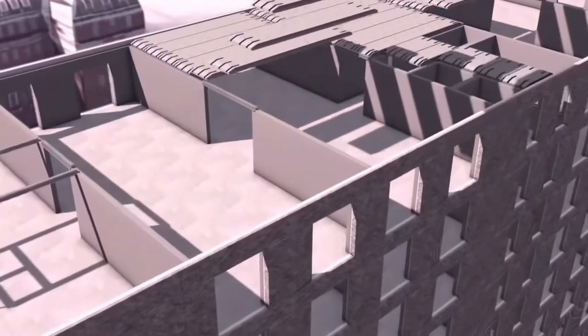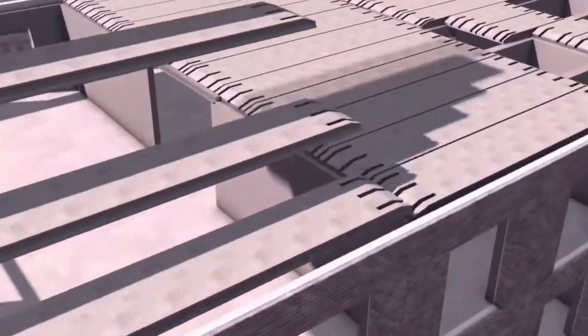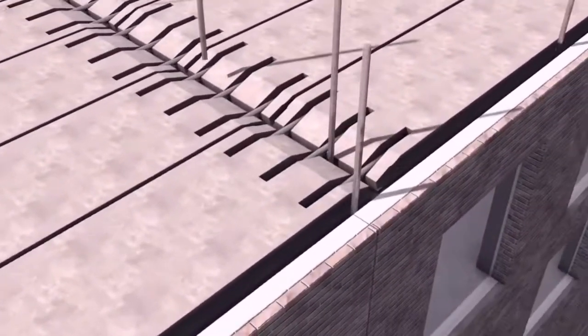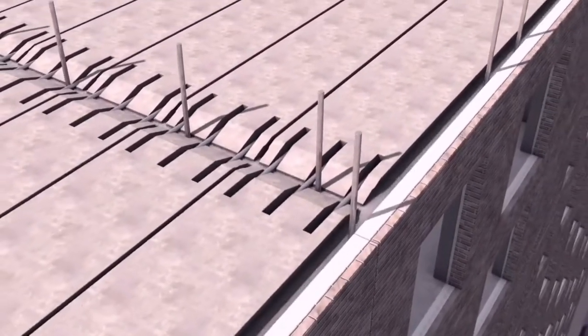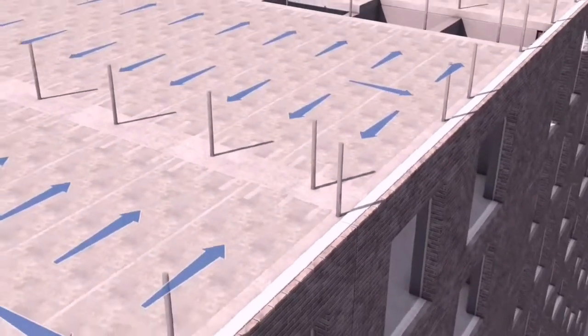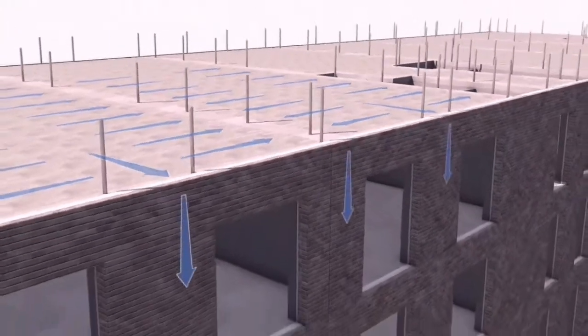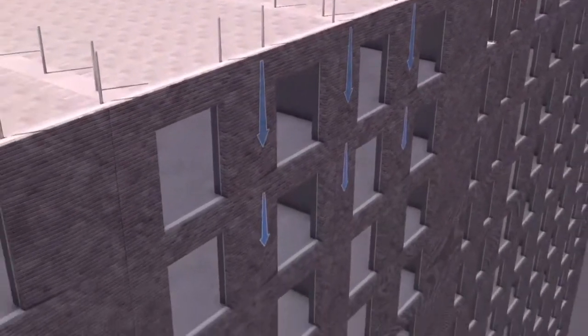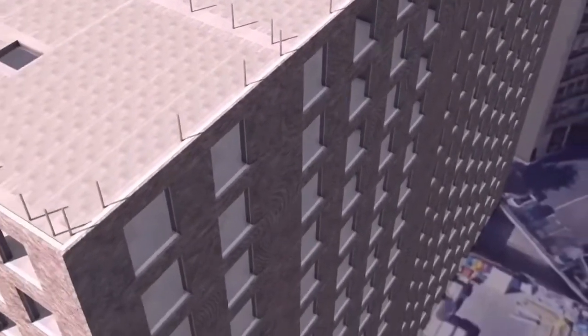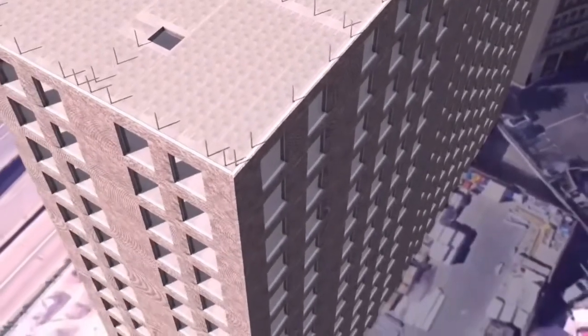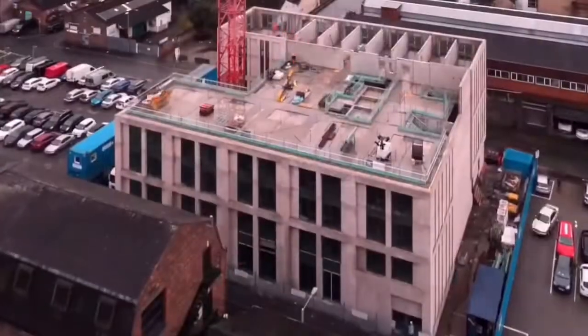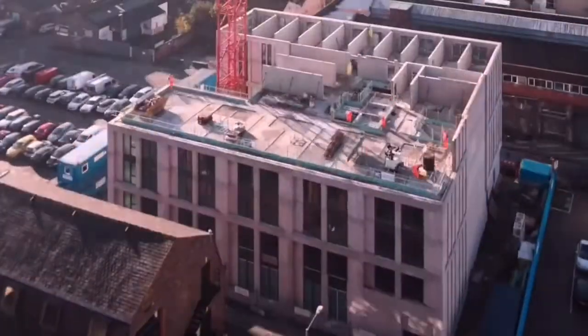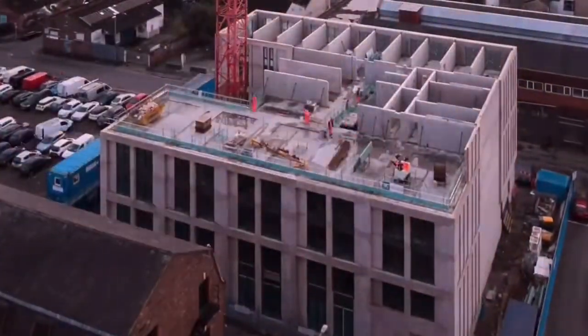Alternatively, hollow core precast concrete planks are used for longer spanning areas. These flooring units are lifted onto their final bearing directly from the delivery vehicle. The units do not require any temporary propping, and once erected, they act as a diaphragm which transfers the lateral force to the cross walls, which subsequently transfer this force down to the foundation.